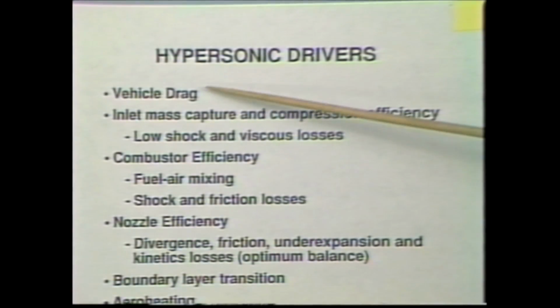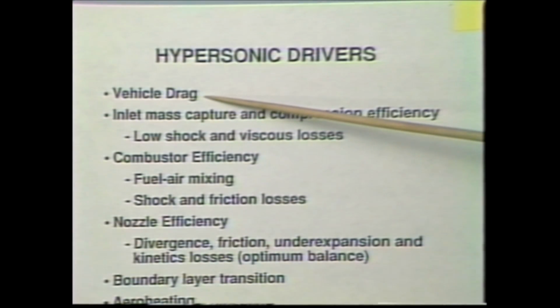That's one of the primary issues in the supersonic regime. Supersonic regime tends to be a fairly insensitive regime from the point of view of performance, but you do have those operability issues of starting the inlet, keeping it started, not unstarting it, adding heat to it. I've pretty much covered those. We'll move now to hypersonic drivers.